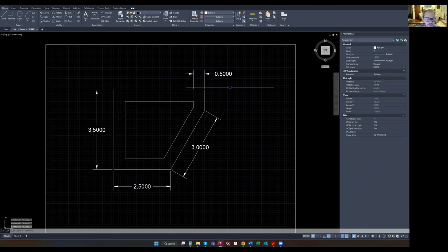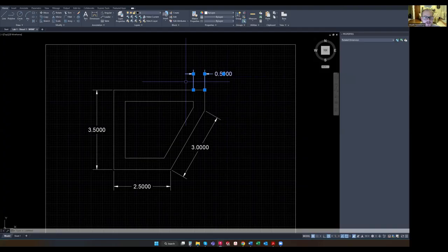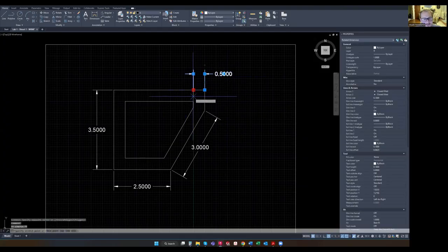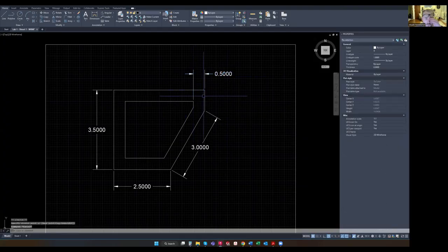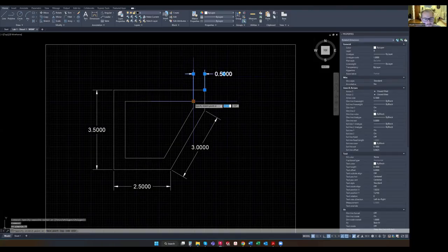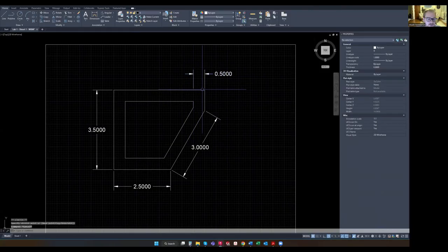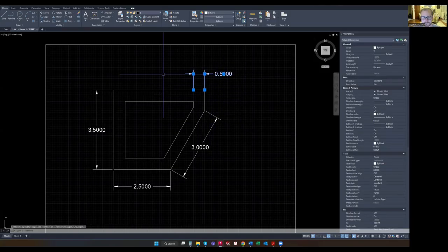And that just makes your dimension look nice and clean, instead of having it dimensioned over top of the part. Depending on the company you're working for and what kind of product you're designing, they may want dimensions through the part, and some companies don't like that. It's all really stylistic, depending on who set it up and what your manufacturer is like. But personally, I like to pull the dimensions off the part, so that's what we're going to do there. Plus, it's good experience to know that you can do that in the first place.